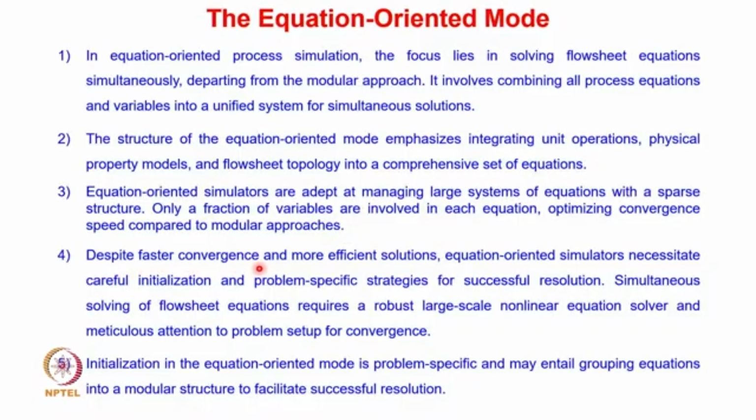So despite a faster convergence and more efficient solution, equation oriented simulators necessitate careful initialization and problem specific strategies for successful resolution. As I said, simultaneous solving of flowsheet equations requires a robust large scale nonlinear equation solver and meticulous attention to problem setup for convergence.